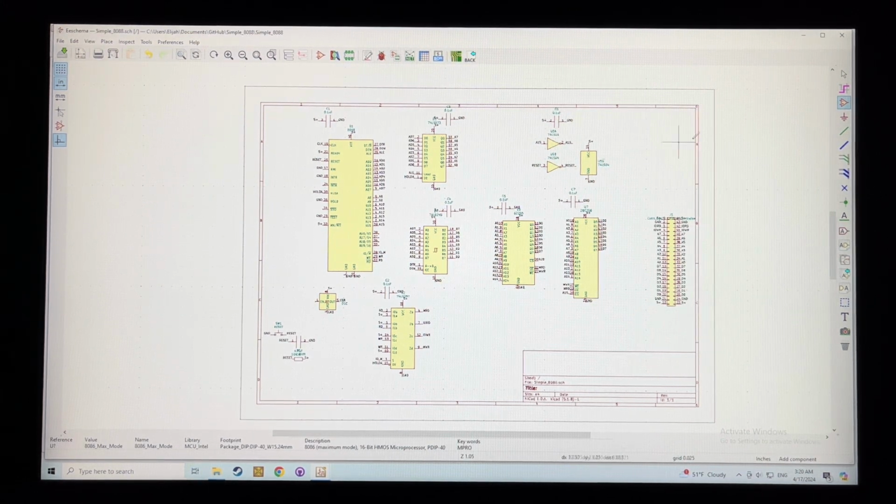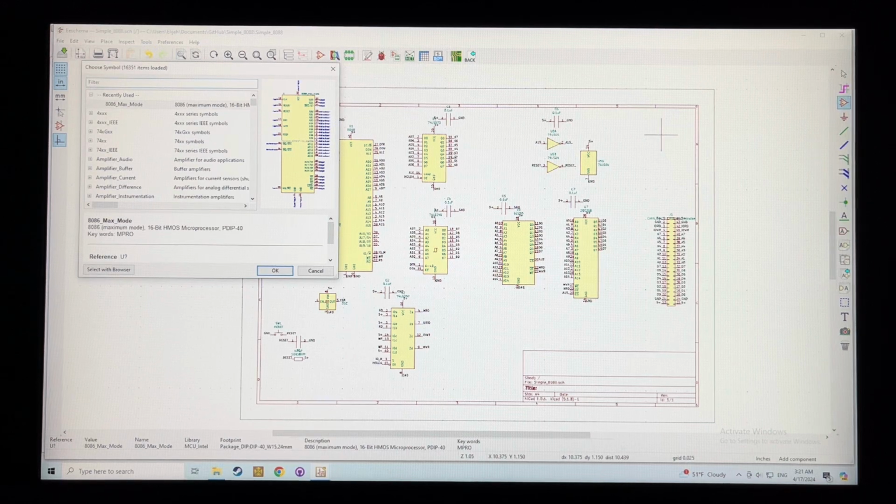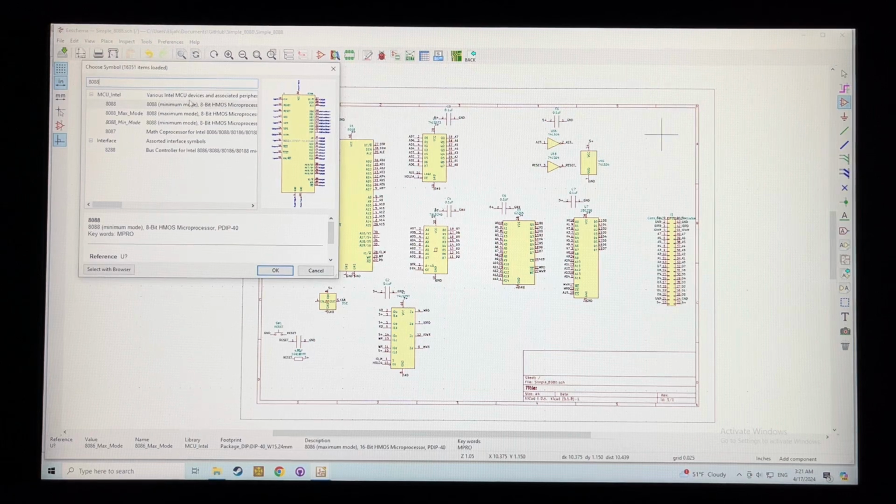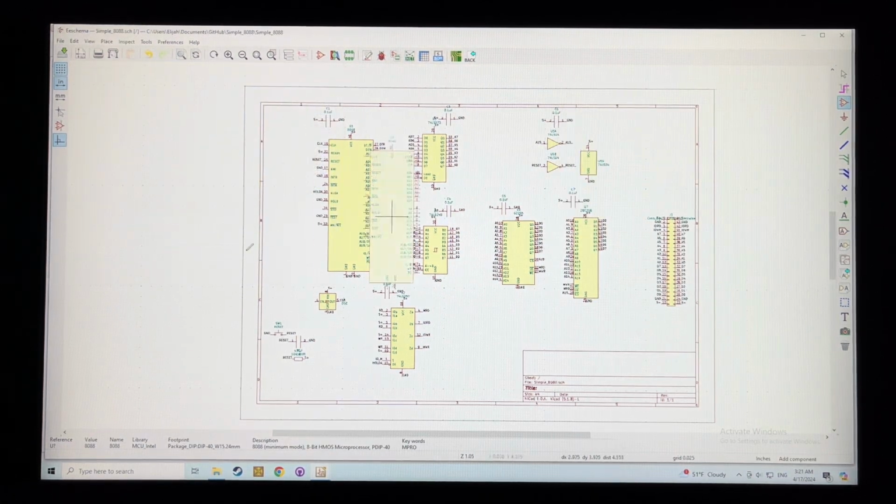So you're going to want to lay out all your footprints first. You don't have to do every footprint, but as many as you can up front, so you get as many on the project as possible. You can always add later or delete. To put new symbols, you come here to the place symbol tool, click that, click on your screen here, and this box will open, and you can search for whatever you want. So let's just say 8088. It gives you a few different options. You select one, and then you can just place it.